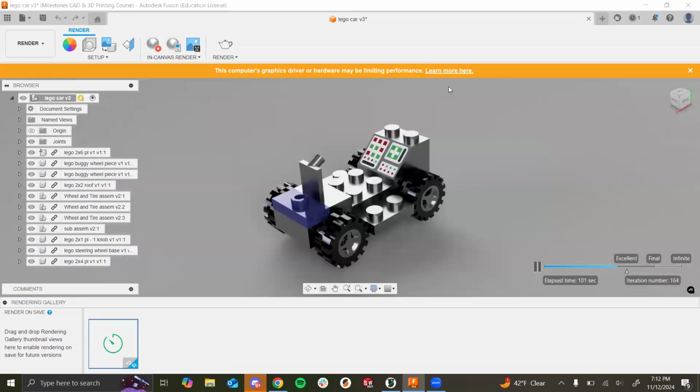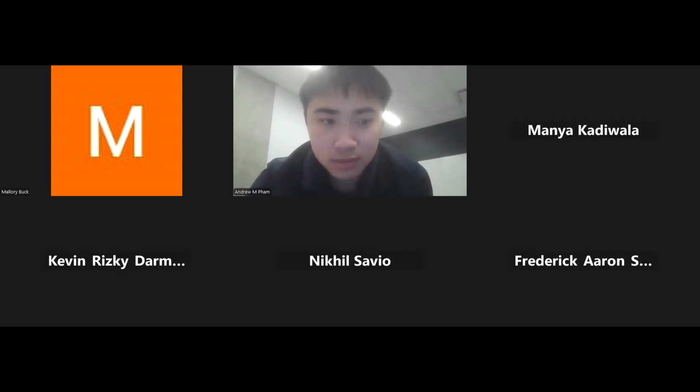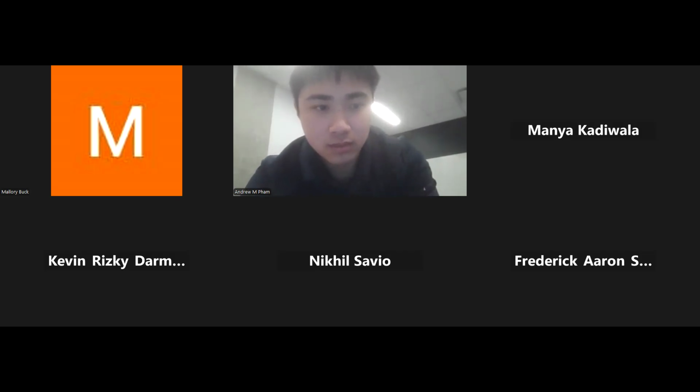The settings I have in this, anything above 60 degrees, it works. But if I set it to like 30 degrees, the tail will have support. And also the cat's head will also have support. Oh, yeah, because that's also 45. That's above 30 degrees. Those are the three supports. Yeah, those are the tricks.